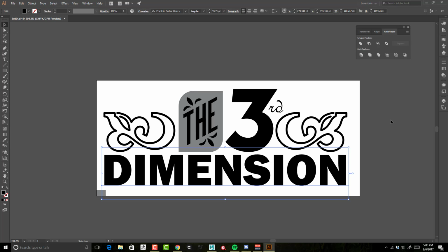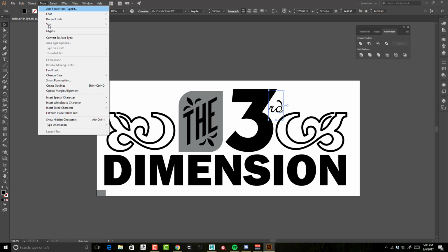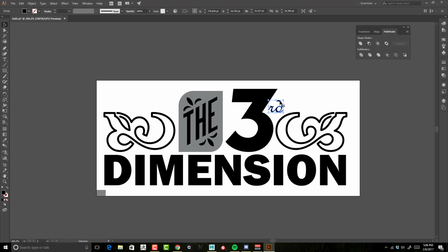All right, so next we're going to jump into Illustrator and show you how to get these Illustrator files into Maya as 3D objects. Now, if you do want to use something that's included in Adobe Typekit, as you saw before, it didn't work using the type tool. So basically what we can do is create them in Illustrator and then just convert them to a shape. For example, this RD here, I just need to go to type, create outlines, and that turns it into a shape that I can then bring into Maya.